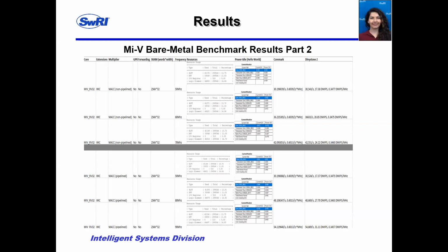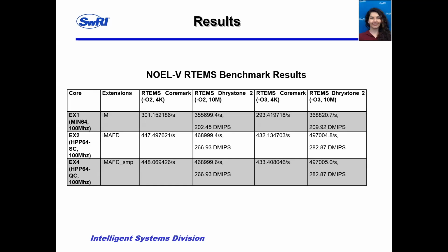Both had identical performance at 50 MHz, showing that instructions per clock of both architectures were roughly the same. Also, interestingly, the MACC multipliers took up almost no more device resources or power draw compared to the fabric multipliers on the previous slide.